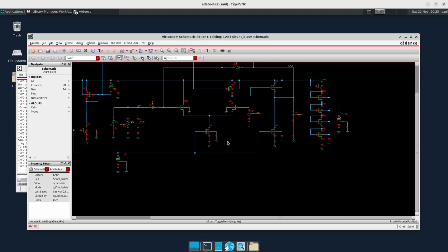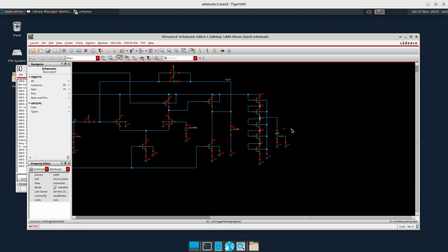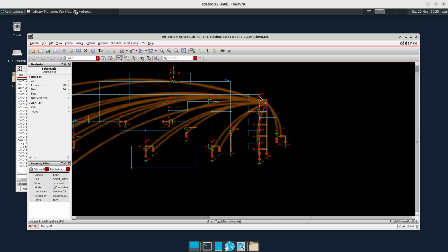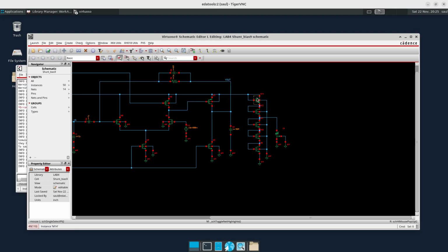If that voltage reference is not available in the chip, we might need to derive one ourselves, and then we can use one of the circuits that we have studied. In this particular case, I use one that is very simple. It is just diodes. We have diode-connected transistors in a row, so they are working basically like a kind of voltage divider.